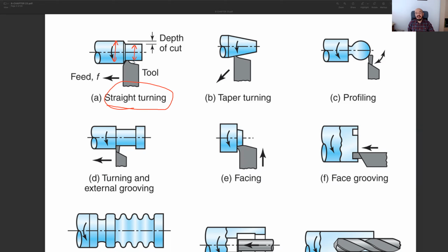We are decreasing the outer diameter, and with the help of this motion, we can improve the surface quality. Probably these unmachined regions have lower surface quality, probably they are corroded, but once you do machining, you'll have polished, burnished surfaces. Their surface roughness values will be low, and they will be shinier. And obviously, this is the depth of cut, as you know.